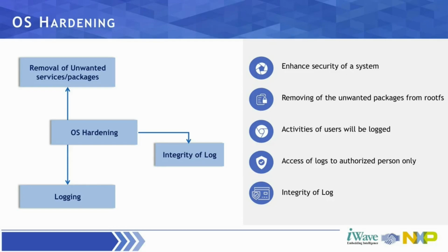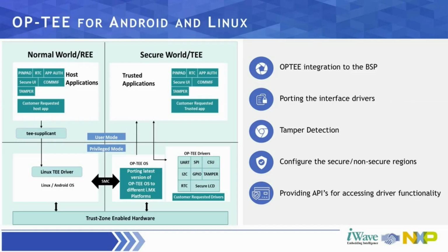Now going a bit deeper into OP-TEE, Silvano did mention the OP-TEE for Android and Linux support on the NXP i.MX SoC. But what exactly is OP-TEE? The trusted execution environment is basically an environment where the code executed and the data accessed is isolated and protected in terms of confidentiality. So it adds a layer of security where the code or data running in this trusted environment cannot be exposed to the normal environment.